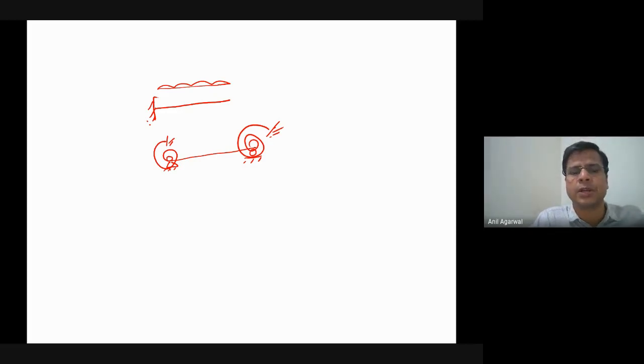It is distributed over an area, and you may have some kind of a spring support. So there you may have some moment coming in. So the moment diagram that I had plotted was like this, but instead it will turn this way because of the presence of the springs. You agree? So a pure simply supported bending moment diagram would be like this.